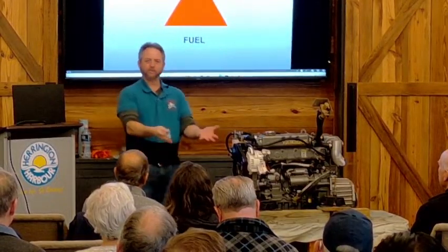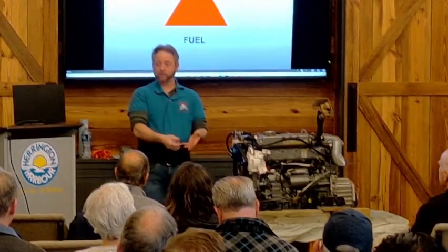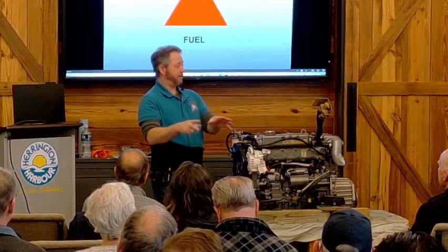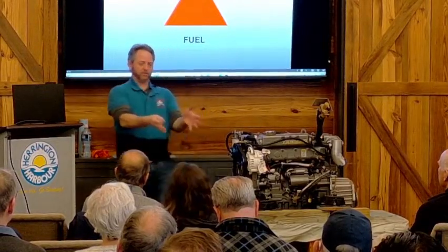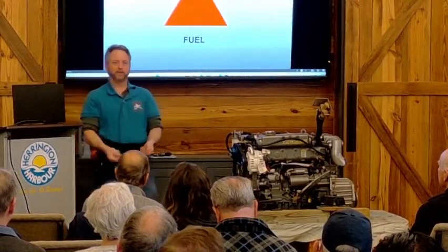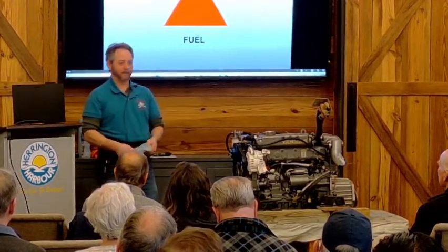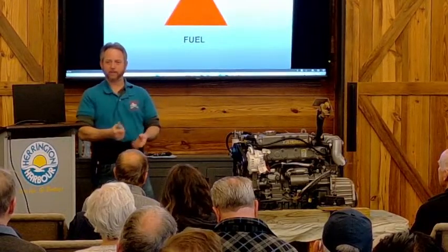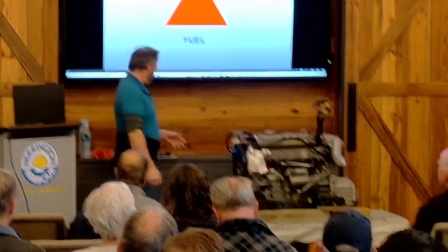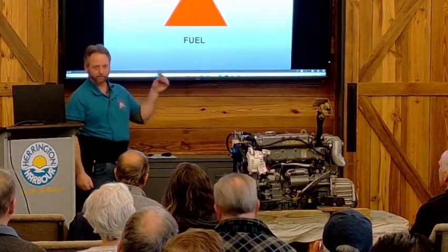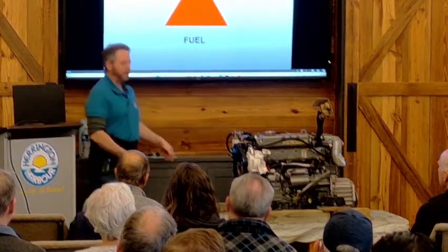And if I took those 5 pieces and ran them through a wood chipper, put that in the fire pit, I'd have even more flame and heat. Now, if I took those wood chips and turned them into sawdust and lit that on fire, I'd get a lot of heat very quickly. So we're trying to get the sawdust out of our injectors and not the log. So surface area matters.